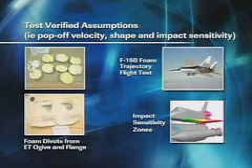And so we need to understand how debris comes off, what velocity it comes off, what the size is, what the shape is. So we did a number of ground tests in all of the element projects to deal with that. And then on foam in particular, we flew foam panels up on an F-15 along the shuttle trajectory, all the way from basically the ground up to Mach 2 and 50,000 feet, ejecting foam divots to try to make sure we really understood the aerodynamics of the divots.